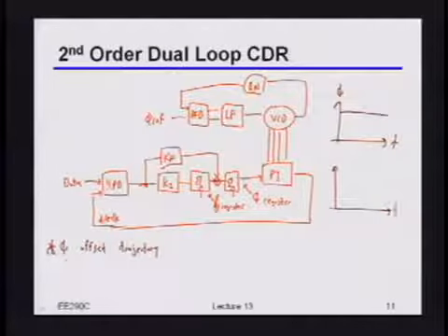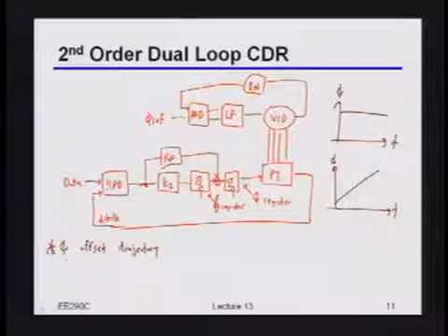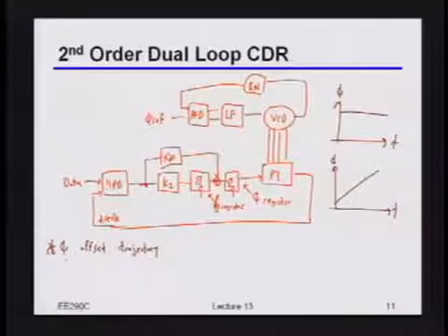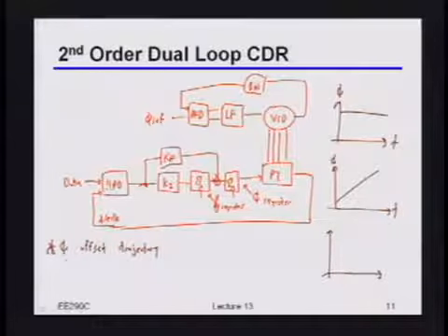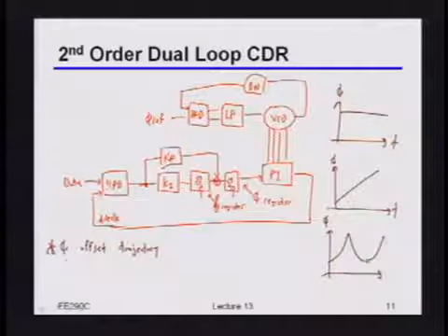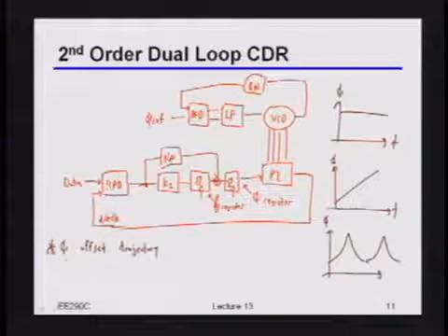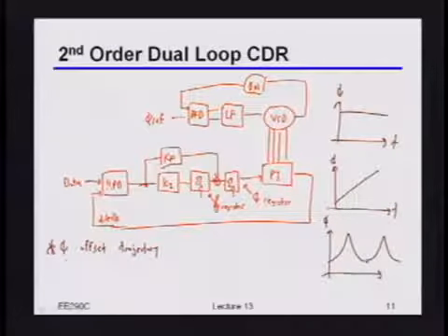If I have a plesiochronous system, then my trajectory has this ramp. So again, I better build my loop so that it can estimate both the offset and the ramp rate. And in fact, it turns out you can even do more sophisticated things. For example, sometimes people have phase trajectories that even look something like this. Okay? Anybody know where that actually comes from? Because the offset is also varying.